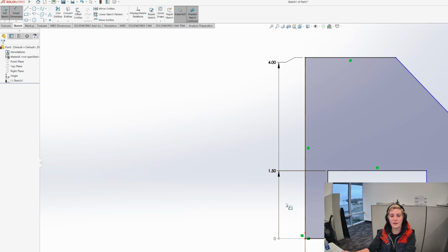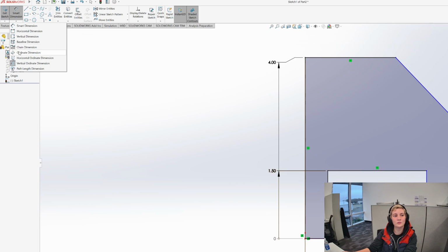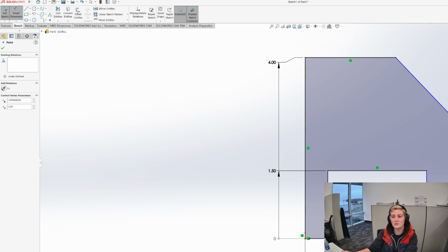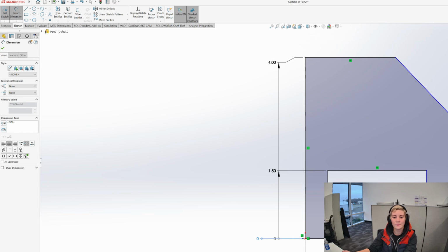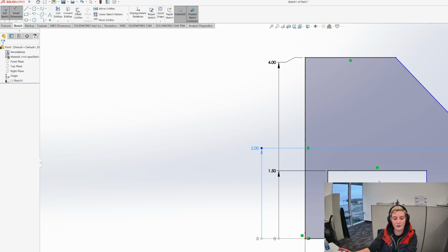Okay, yeah, I see what's going on. So when you exit your dimension tool and then you go back in, it's going to put a 0 wherever you click. So like I left and I came back. Now it's going to put a 0 here. So what you need to do is click here again to make that your 0. And then you're going to click whatever you want to dimension from that point, and it'll put that one in for you. Does that make sense?